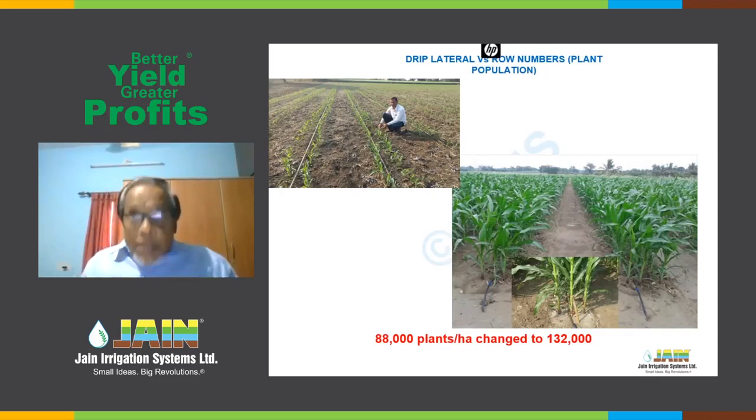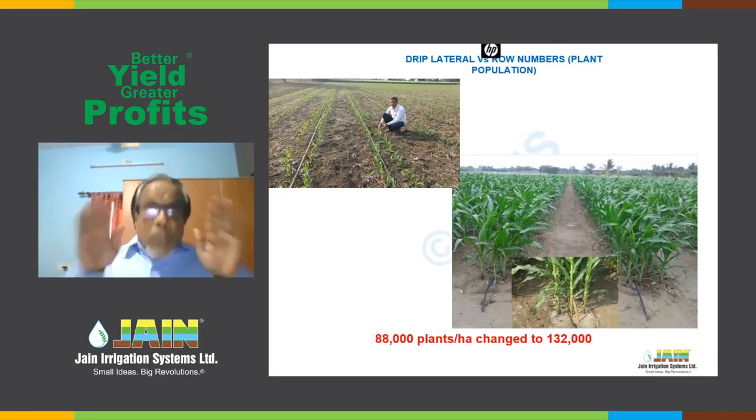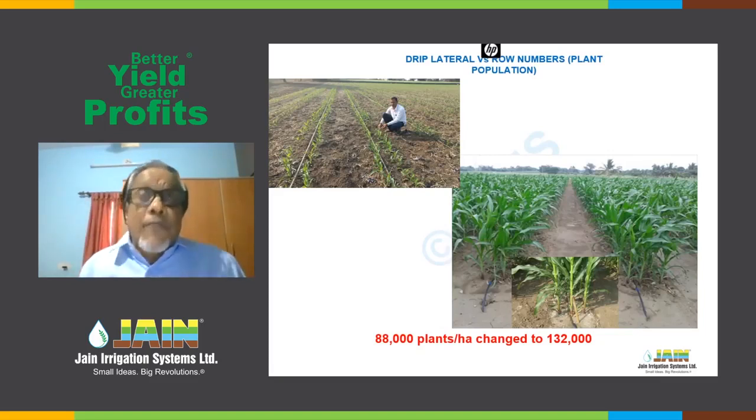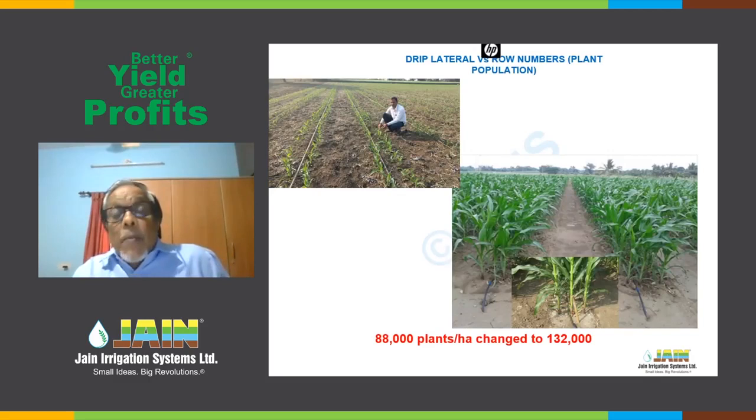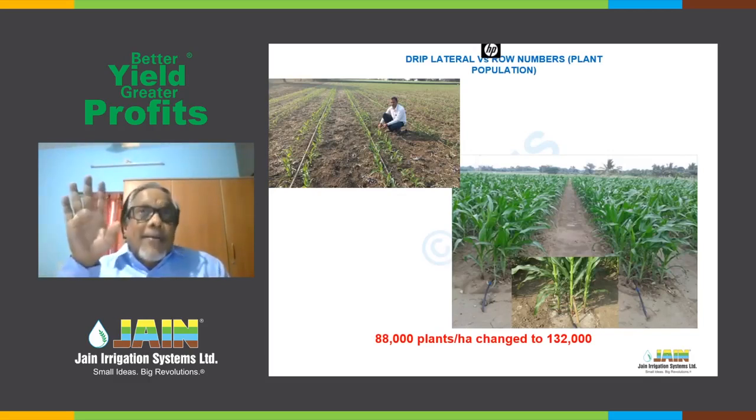This is a case where lateral spacing, for economic reason and the reason of equity in the society, is already decided. Similarly, the water volumes that can be delivered is also decided, and it is a deficit quantity of 2.5 millimeter only you will get. In other words, per hectare he will get 25,000 liter water only. Maybe in the early season you don't need that, but the point is that cuts away most of the land surface from getting wet. That's the point.